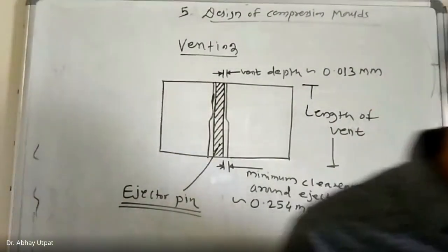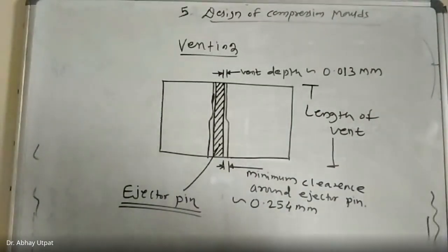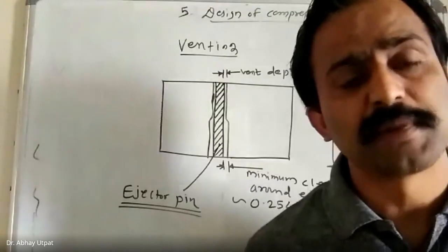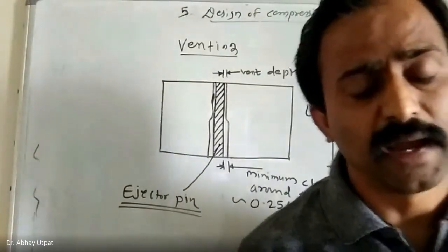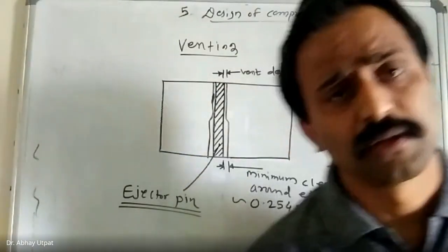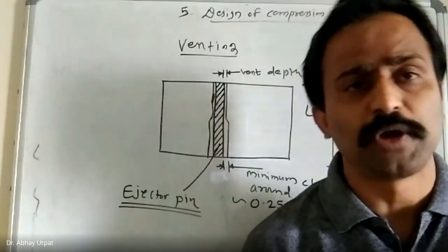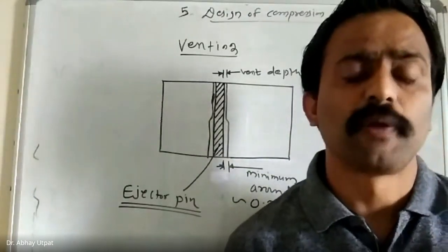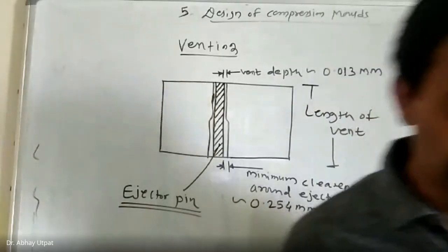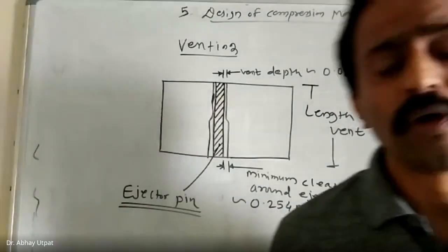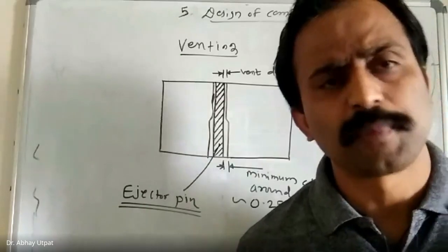So you should remember this as far as MCQs are concerned. Then you must remember the minimum distance between thermocouple and heater. The optimum distance maintained between thermocouple and heater is 1.25 inch to 1.5 inch. If that distance is less, cyclic on-off of the thermocouple will be observed.